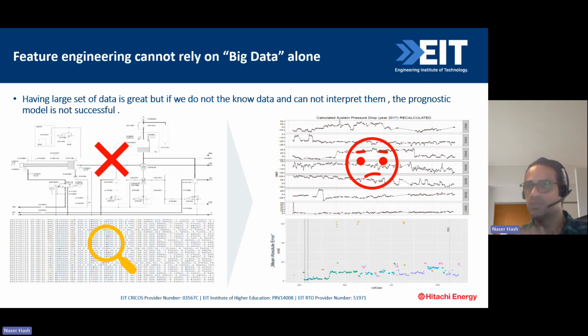So to apply this solution to each piece of equipment, we really need to understand how the process is working. If you have power generation, a steam turbine or a gas turbine connected to a generator, and the generator is connected to the bus bar, and the bus bar to a transformer. For this complex model, first of all, we start with the single line diagram to understand how the model is working. Then we need to understand what data is coming.